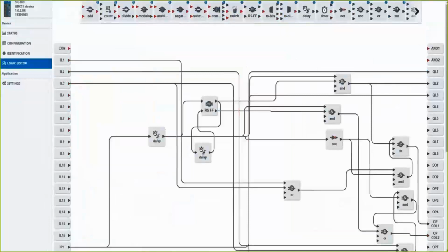Okay, so here's a highlight of the SIG100, and there we can see IL1 on the left-hand side. Now, it's not referred to as S2 IL1 because the SIG100 hasn't got any ports of that nature. It can only have digital I/O. So as far as the SIG100 is concerned, it's just IL1. If you had multiple SIG100s connected to your SIG200, then you would have S2 IL1, S3 IL1, S4 IL1, etc.